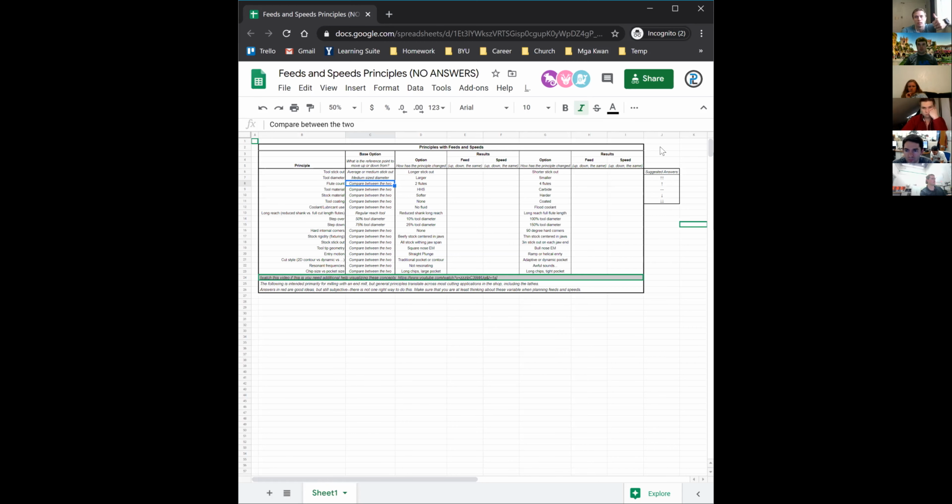One, these are my opinions. They're not necessarily correct because there are so many ways to skin this cat. For example, Tyler talked about harmonics. If you are getting harmonics, you can move your spindle speed up or down and possibly avoid that harmonic. So there's not one right way. But I still want everyone who's running a CNC machine or even a manual machine to be thinking about these different principles and how they can affect your feeds and speeds.